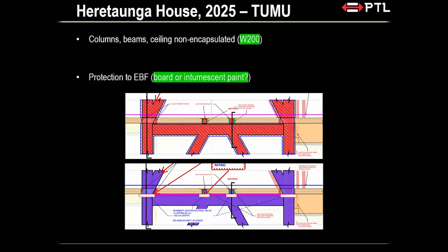So there's this boarded system where you just board up all your steel. And as a result of boarding up the steel, you also solve the problem of your penetration. So these two are notched into the CLT floor. And then these two on either side are the continuous steel column. So you encapsulate the bottom, encapsulate out at the top, doesn't see the hole, no problem, right?